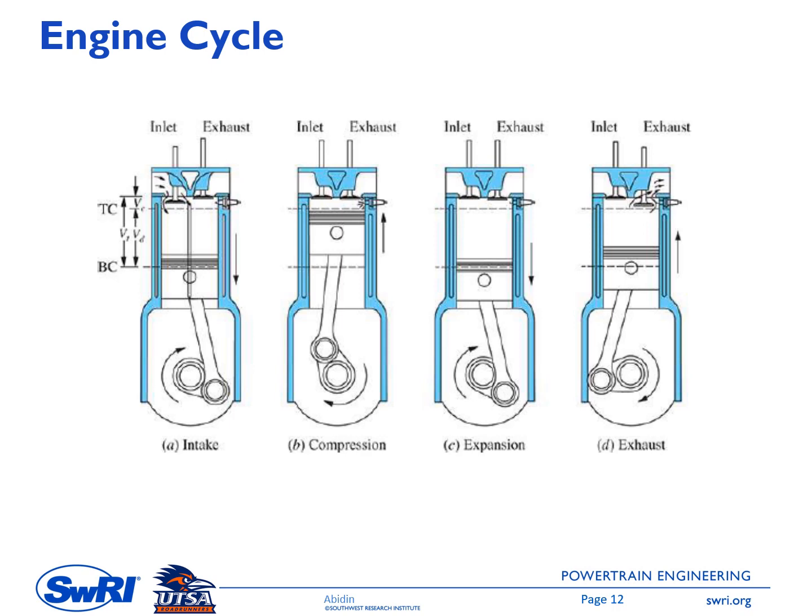So in the first figure on the left side, this is an intake stroke. In this intake stroke, the piston moves toward bottom center. Okay, so it moves down. This means that the chamber volume increases and the chamber pressure decreases.